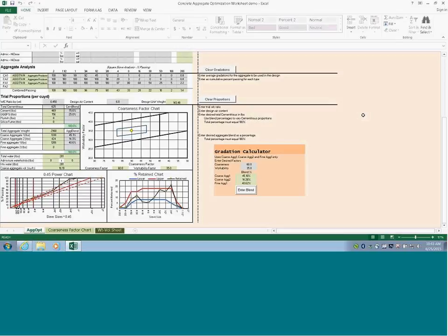Well, I have my question is, by 7 and 8 grade without having to blend a second aggregate? Well, what you'll have to do with that is, when you enter them, you'll need to play around with over here. You play around with the aggregate blend area here. You see where I'm pointing there? Yeah. You have to play around with that until you get it to where you want it to be. That's all. I mean, 60-40, and then play around from there. Sure. It would have to be an awfully coarse fine aggregate for you to get it in the box, I think. But it's possible.